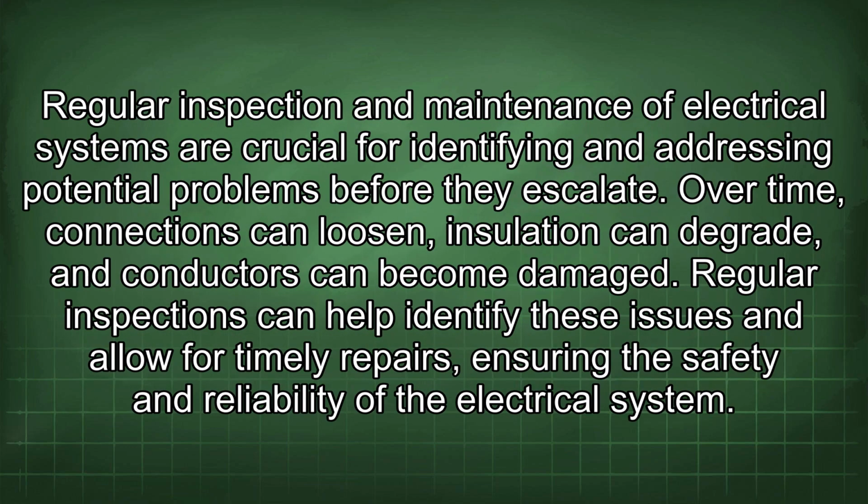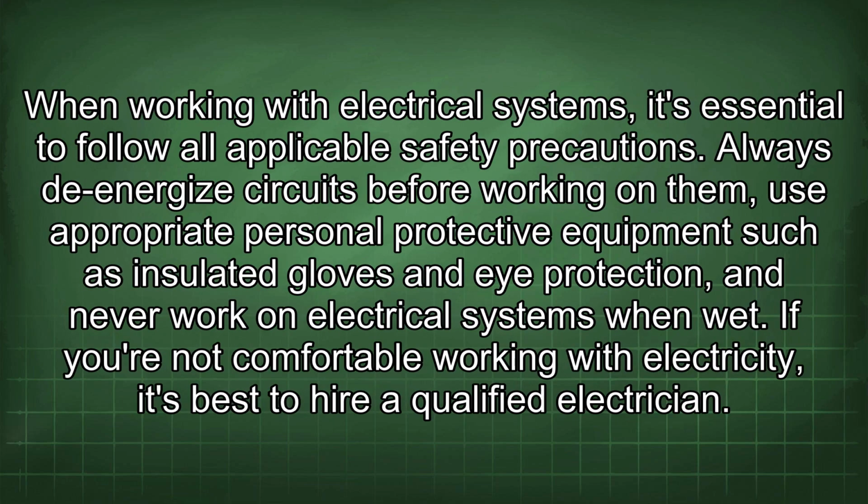Regular inspection and maintenance of electrical systems are crucial for identifying and addressing potential problems before they escalate. Over time, connections can loosen, insulation can degrade, and conductors can become damaged. Regular inspections can help identify these issues and allow for timely repairs, ensuring the safety and reliability of the electrical system.